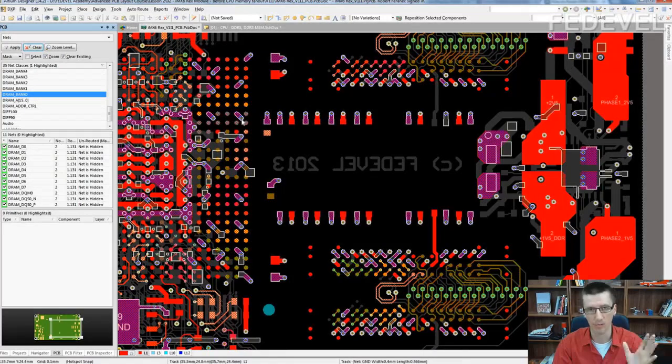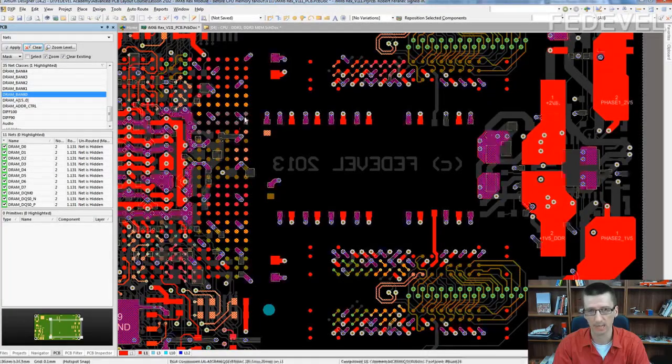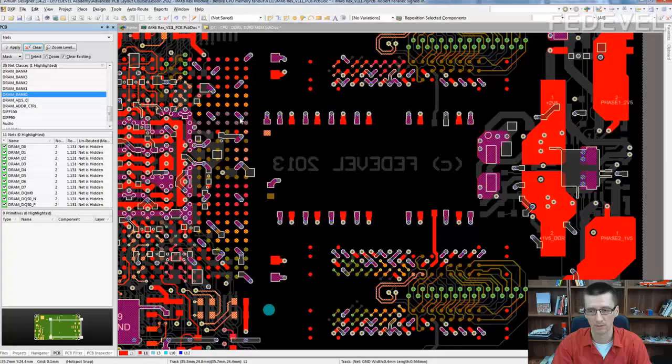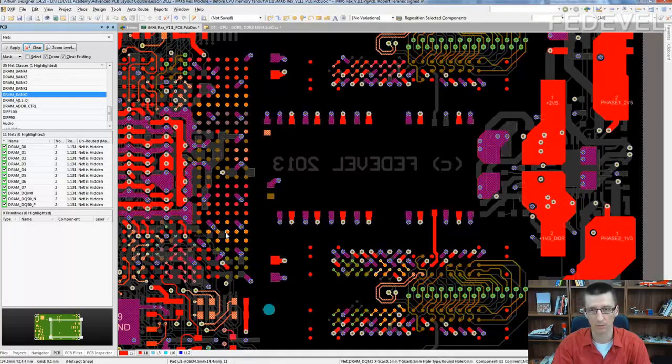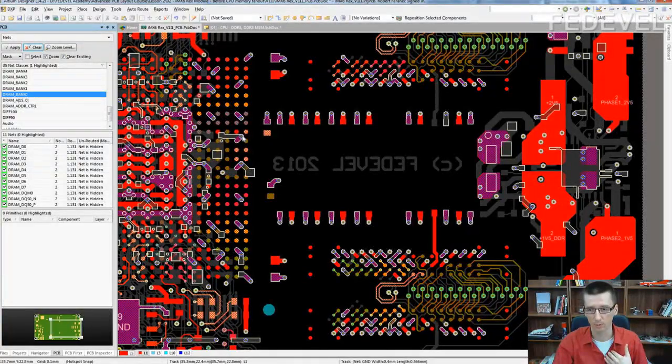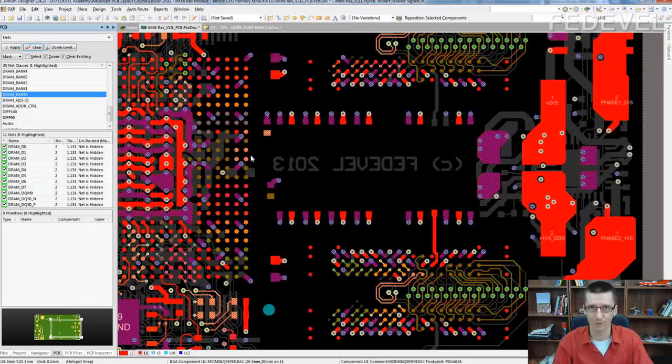And you finish your DDR3 layout, and then when you start placing these vias, you need to move the tracks. You need to make space for these vias. And there will be a lot of tracks. You need to move a lot of tracks. And it's not necessary. When you place these vias before you start doing the layout, you can just go around and that's it. No additional work later. I'm sure you understand.